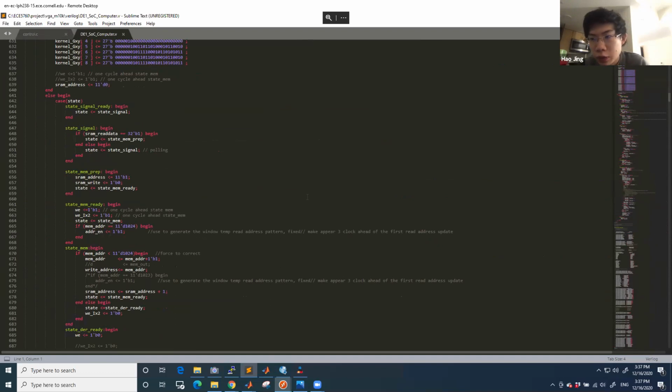Once it's sent to the FPGA, one more thing we did is add a padding of zeros around the image, because we are using a 3 by 3 window, which means we need one more column and one more row, because otherwise we have holes outside the picture. So we just add 0s outside the picture, which makes it 32 by 32. Basically, the image we have is 30 by 30, and the window we have is 3 by 3. So the image we send to the FPGA through SRAM is 32 by 32.